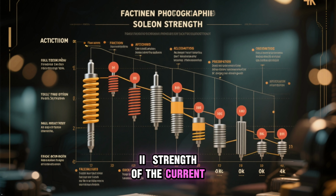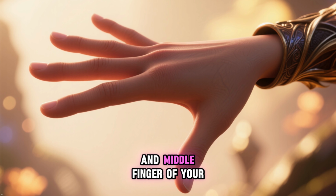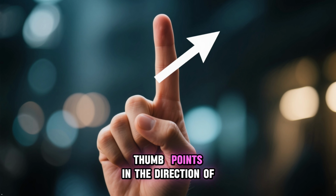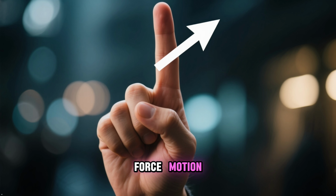Fleming's left-hand rule. This rule determines the direction of force on a current-carrying conductor in a magnetic field. Rule: stretch the thumb, forefinger, and middle finger of your left hand mutually perpendicular. Forefinger points in the direction of the magnetic field. Middle finger points in the direction of the current. Thumb points in the direction of force or motion. Memory aid: Father thumb, force; Mother forefinger, magnetic field; Child middle finger, current.